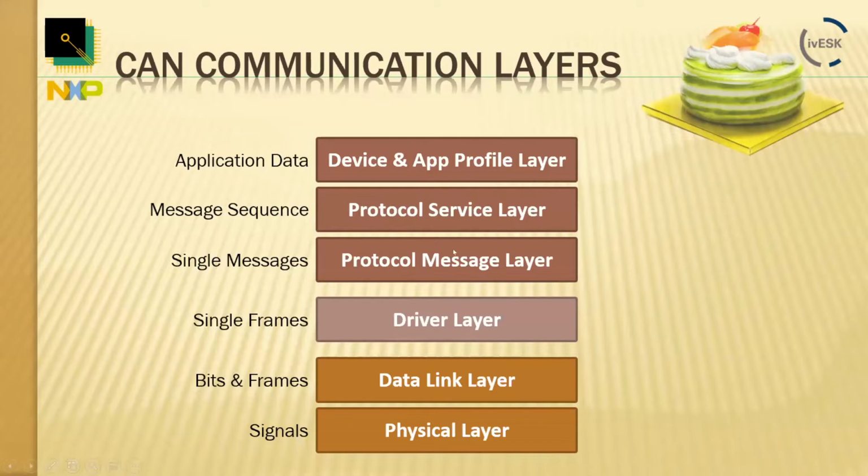If we look further up, and there's a protocol stack involved, J1939, CANopen or anything homebrew, then at this point there will be some layer where we look at single messages of this protocol, the message layer. At a little bit higher layer, there will also be message sequences, so multiple of those. And somewhere on top, of course, we have an application layer.